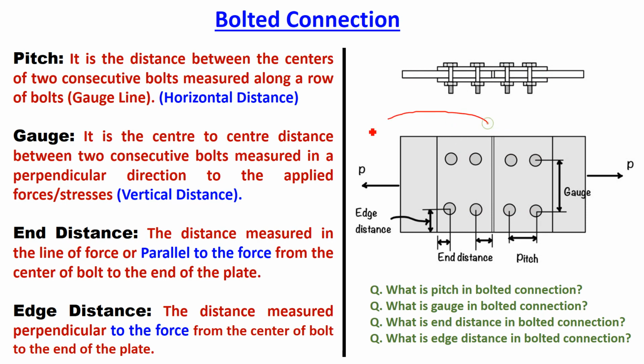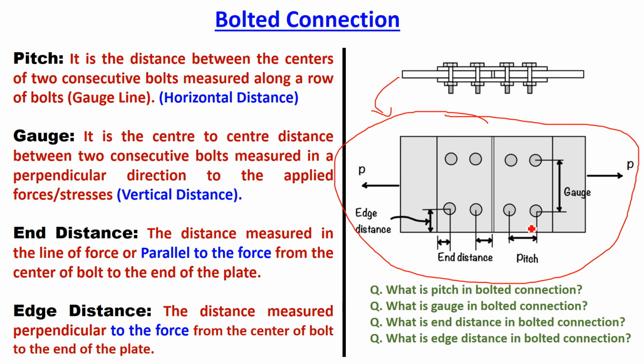Now if you look at this top view of this connection, the very first terminology is pitch. That is the horizontal distance between two consecutive bolts. The horizontal, center to center distance between two consecutive bolts is called pitch. So this is pitch, right?